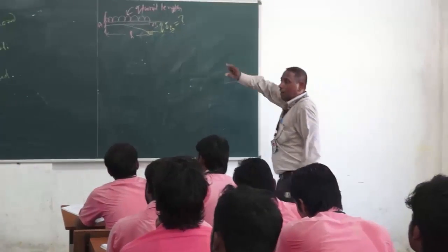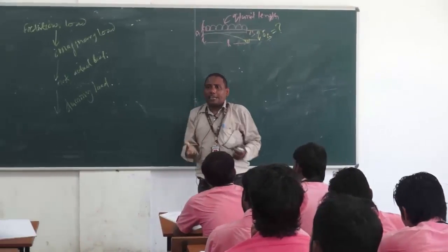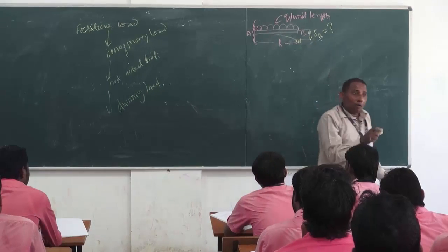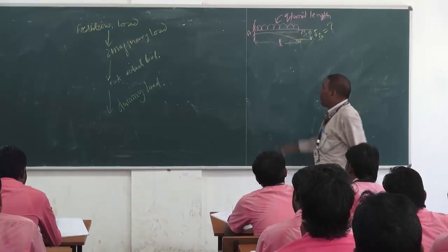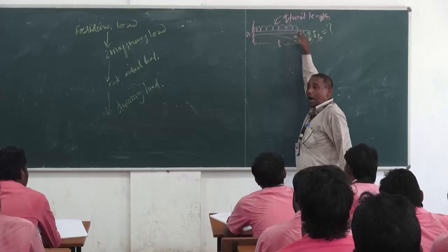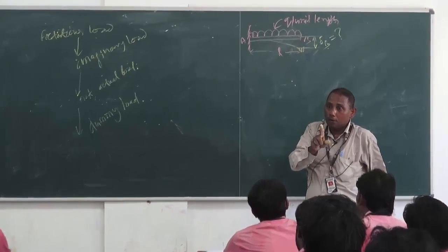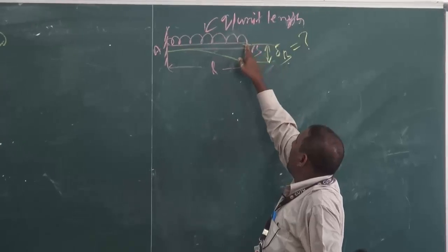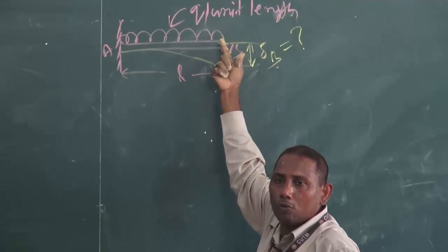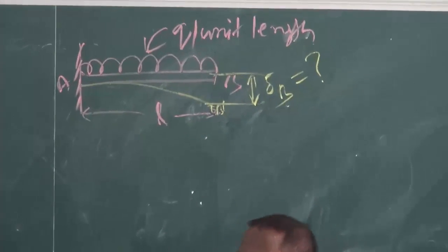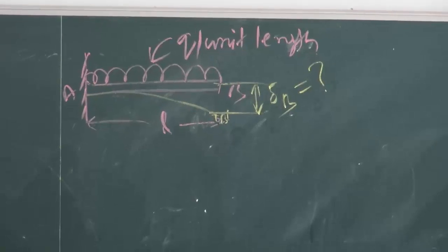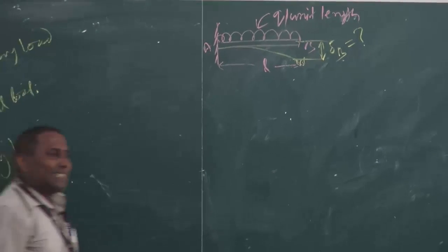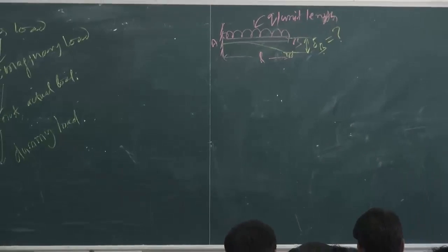And we require the deflection there. You see here, in the ordinary sense, you cannot apply Castigliano's theorem here, because for Castigliano's theorem, a point load should be applied at the point at which the deflection is required. I require the deflection at point B, delta B, but is there any point load at point B? No. So ordinarily Castigliano's theorem will fail. But it is not applied in particular, it is a general theorem. It can be applied to any situation.